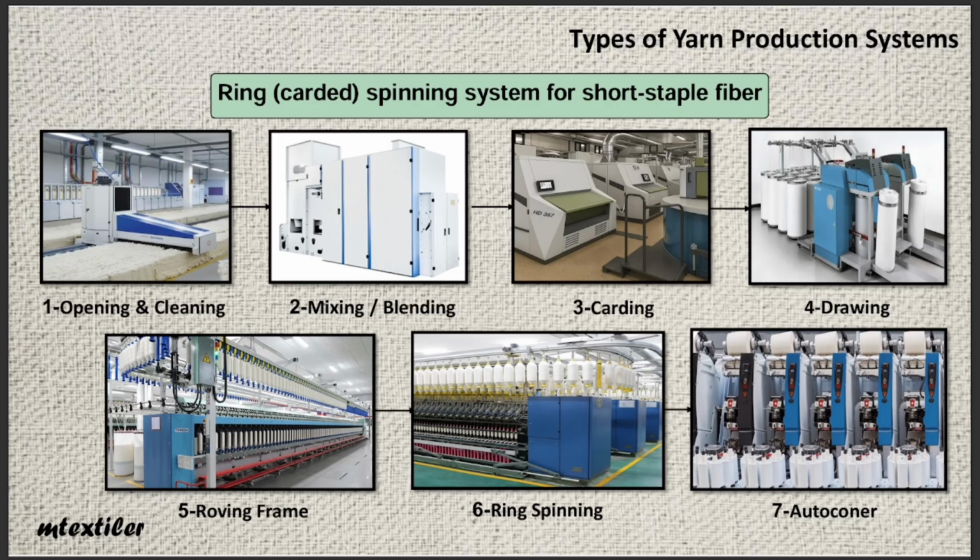To evaluate and monitor the performance of the previous two machines, this intermediate product, the sliver, is tested in laboratories. The next machine is drawing, whose functions include mixing fiber slivers and drafting several different slivers together so that the fibers become straight and parallel again, returning to the thickness of a single sliver. The number of carding and drawing machines depends on the production rate and the overall capacity of the production process in a factory, and is determined at the initial installation and setup stage.